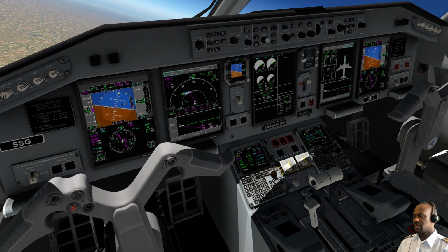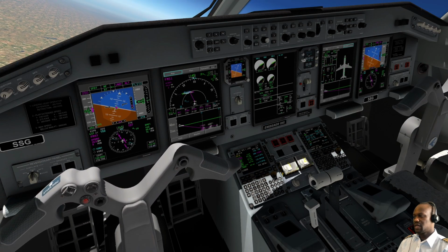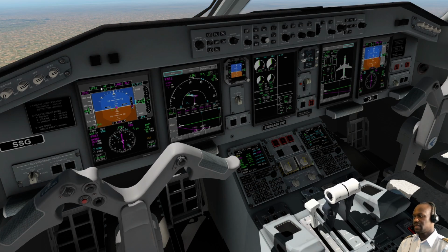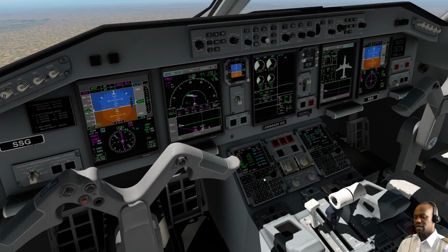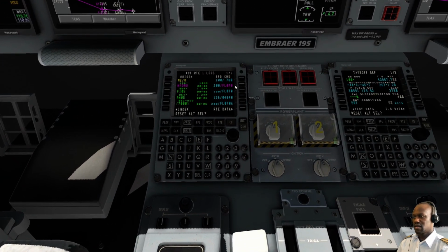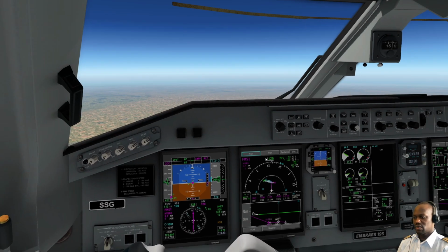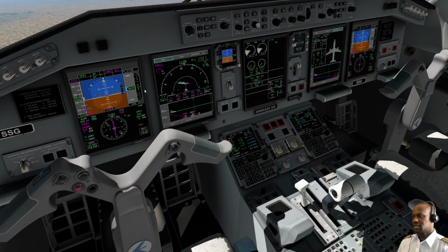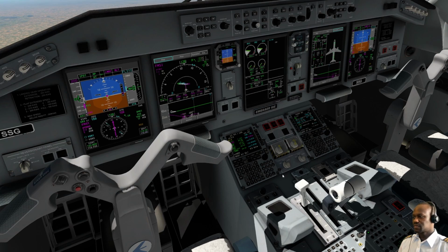Okay, that's position November Zulu. The aircraft is still maintaining flight level 310 as expected. We can now see the speed reducing to 200 knots. 200 knots was the planned speed at position Hydro. So the aircraft is still anticipating 200 knots and therefore reducing the speed. You can see the thrust levers reducing. However, all that is happening at flight level 310, which was our cruise level. Of course, the aircraft will turn towards the runway, but at a very high altitude.